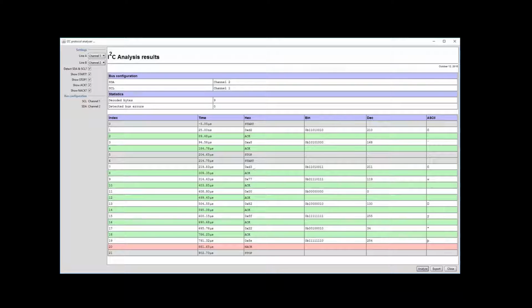Then the slave will send an ACK, and then he sends a series of 1, 2, 3, 4, 5, 6 data bytes, so 3 registers' worth. And this is the NACK, basically the last byte, even if it's valid, will not get ACKed by this master, followed by a stop.